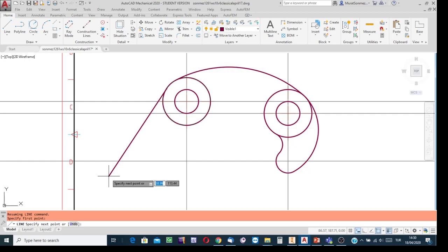But here, if the line has only one tangent point, okay, well, if the line is in such a characteristic, you see in the screen, although the dynamic input button is on, there will be no arc simulation, no horizontal line simulation. And in the third box, you see we have no degree symbol. So, well, be aware, the case is different. Now here, before writing any number into the second box, okay, that box is to input the length of the line. We must say that we are going to write the length relative to the tangent point.